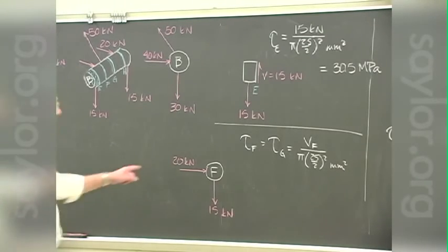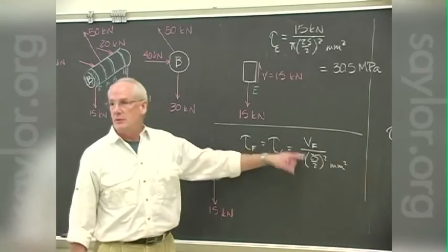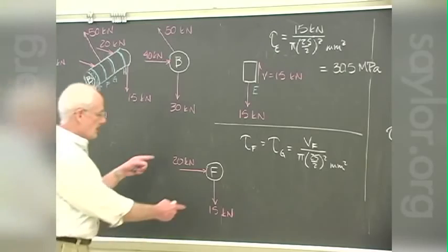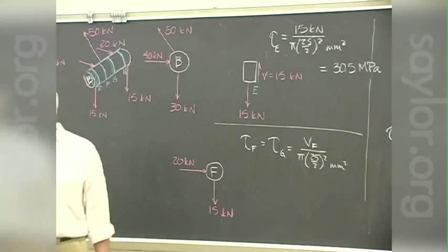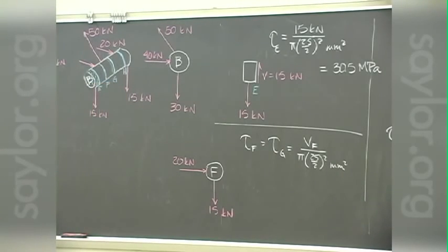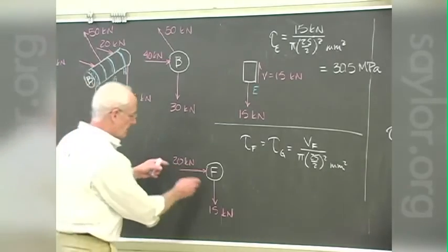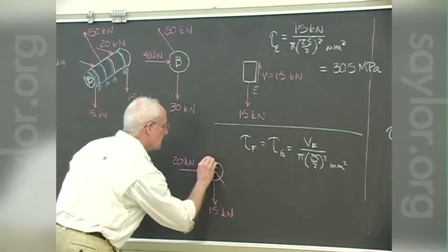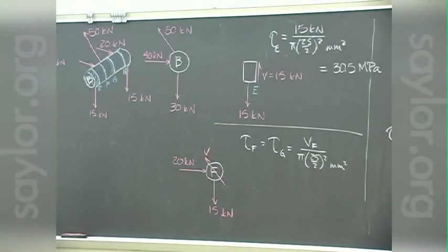Once we know what the shear is, we just put it in and divide, it's real easy. What is the shear there? Is it 35? Remember, we don't add the magnitudes of vectors, we add the vectors themselves. So those two vectors added together have got to be resisted by a shear across the face, something like that.